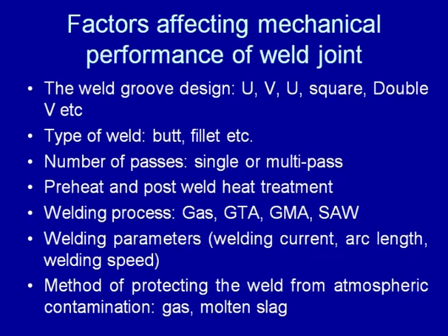Then the number of passes. In general, multi-pass welds, especially in case of thick plate welding, result in better mechanical performance as compared to the single pass weld, because multi-pass welding results in the refinement of the grain structure in the weld metal which was deposited in the earlier passes. So, bead tempering keeps on happening in case of multi-pass welding, which refines the structure and improves the mechanical properties of the weld joint.